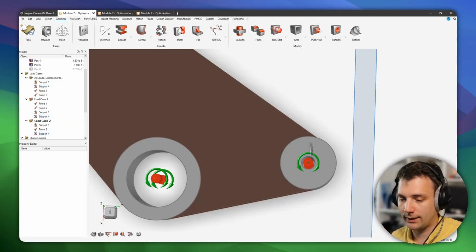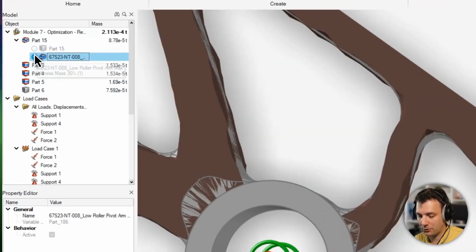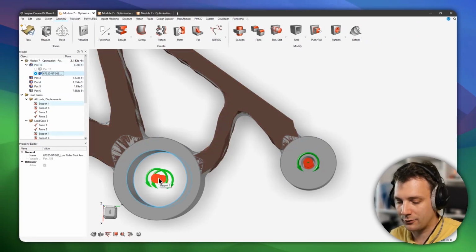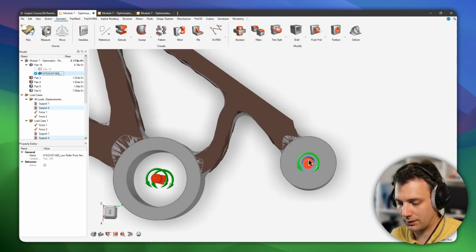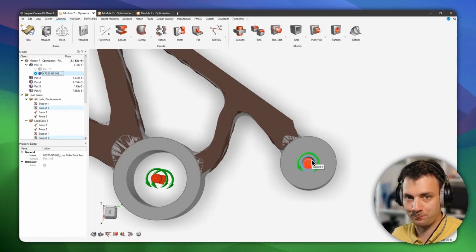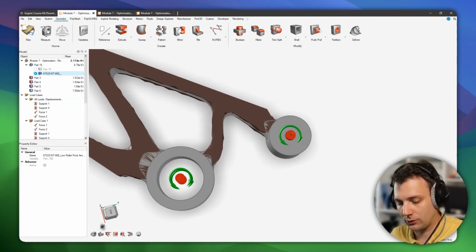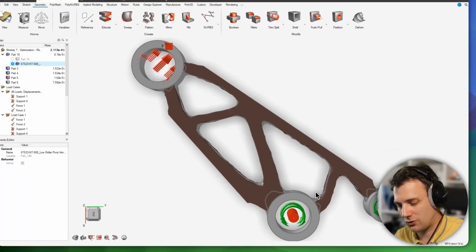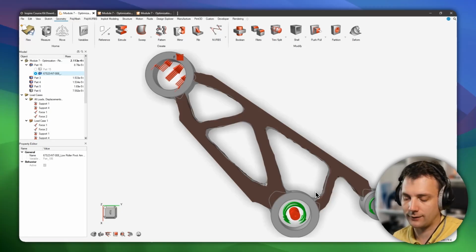And this is why structures like this can be perfectly fine and happen, because if you can make sure that this point does not move with respect to this point, then this structure is not really having any buckling issues, right? But just looking at it, you must judge the structure of what you see and try to make sense out of it, and see then the underlying cause, like in this case the bearing scenario.